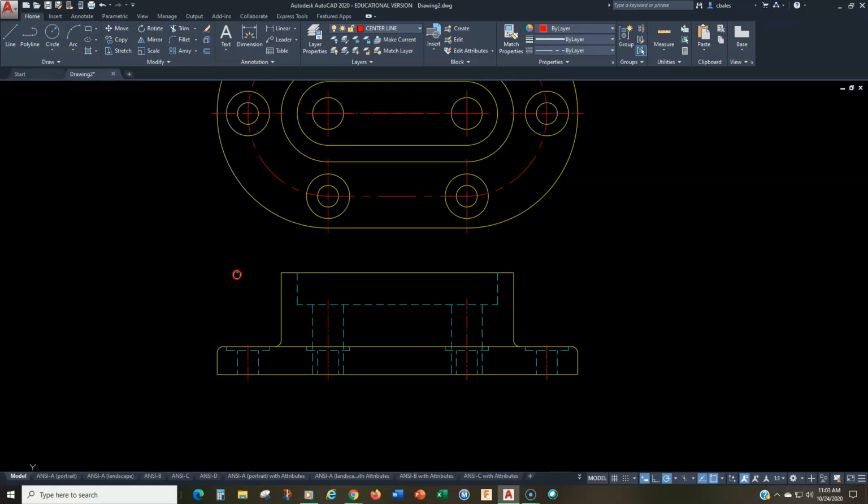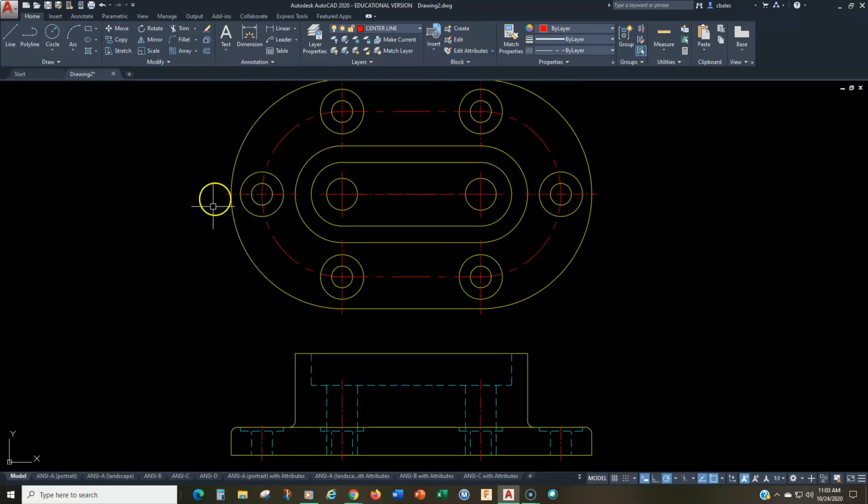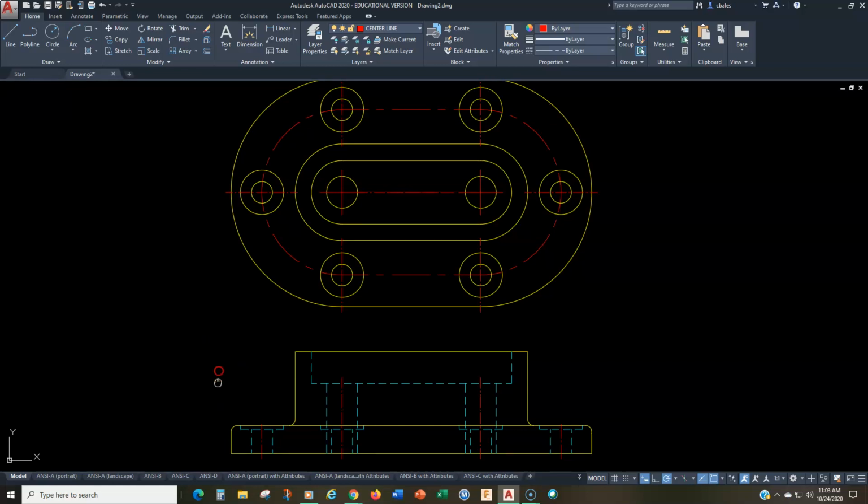Okay, so first things first. These holes out here are dimensioned with a diameter 0.34 and then diameter 0.70, and it says on the dimension in the drawing, S face, and then it says 6 holes, okay? So that note, diameter 0.70 S face, is an old notation for a spot face, okay? And a spot face is basically a shallow counterbore, all right? And so that's kind of what I've drawn here.